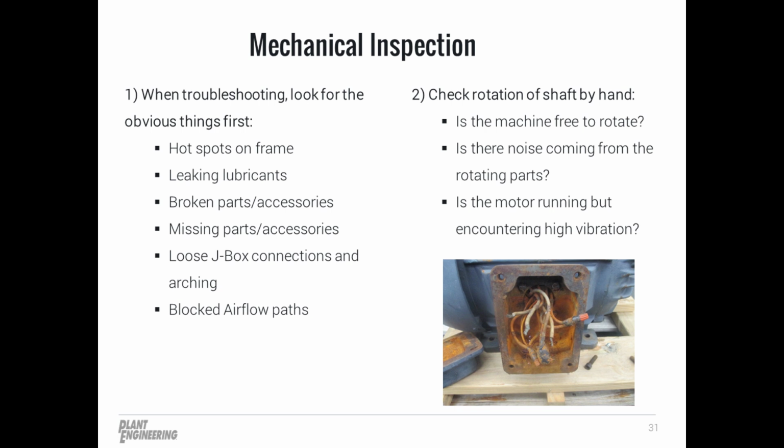A lot of times it's easy to hear or even feel a bad bearing or rotor dragging inside the stator. But in some cases, you're suspecting a mechanical issue before it becomes a failure because you notice high vibration coming from the motor, but not very clear on where the source is coming from. In this case, you'd want to extend your options and perform vibration analysis.